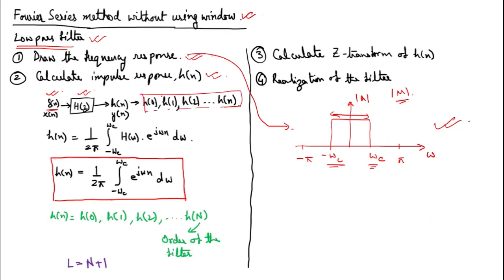Now this series of outputs is related to the transfer function of the system. From this h[n], the impulse response, which is the output when we give an impulse input, can be converted into the transfer function of the system, and these are helpful in calculating y[n], the output of the system when we give an input x[n].